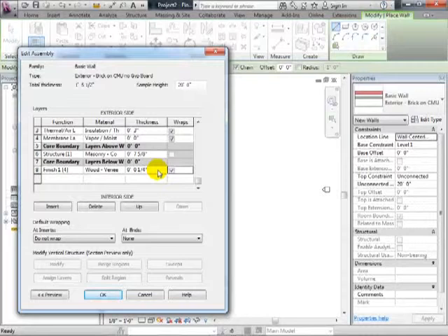But the first thing is really just go ahead and start customizing the wall to really make sure it has all the right layers. Because the whole issue of the layering in the walls is when you go through and cut your section, it's very important the layers are in there, and the closer they are, the less work you're going to have to do later on.